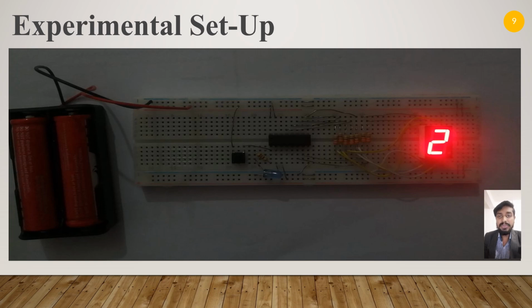We also use the PTM switches, which provide a positive pulse for a short moment. A short positive pulse to the clock pin makes the counter increment by 1, and the 7-segment display would then display the numerical number 1. Further presses of the PTM switch increase the count, and the display shows the count.